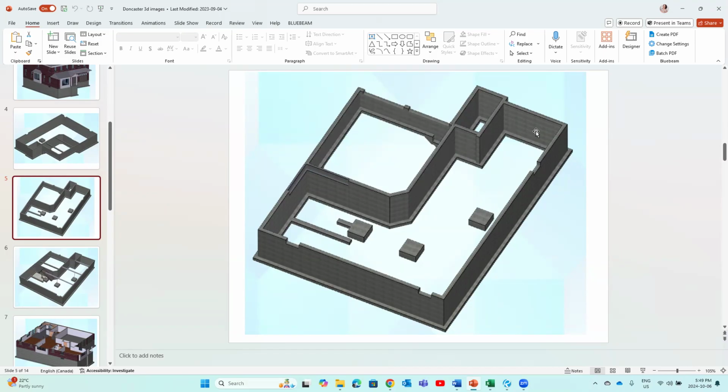Concrete for foundation wall, we use the length multiplied by height, multiplied by thickness, and we get the volume. If we want to get the formwork for the foundation wall, we take the length multiplied by height, multiplied by 2, to get both sides. You guys remember that, right?